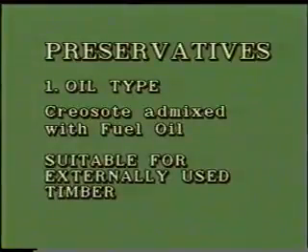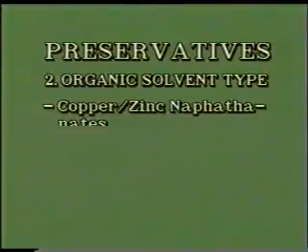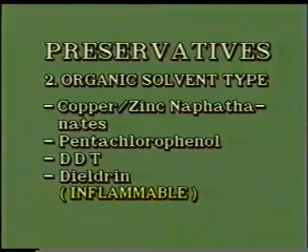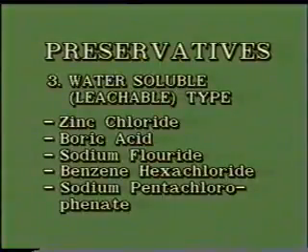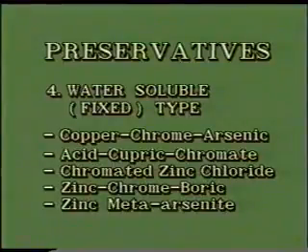There are 4 types of preservative. Oil type preservative like creosote, organic solvent type like copper naphthenate, water-soluble, leachable preservatives like zinc chloride, and water-soluble fixed preservatives like copper arsenic compositions.